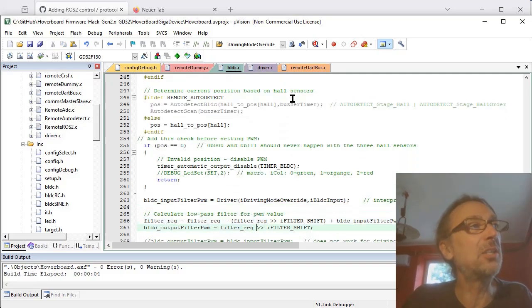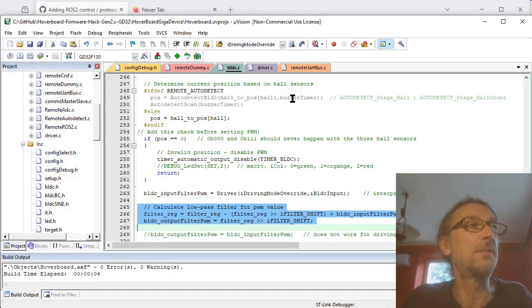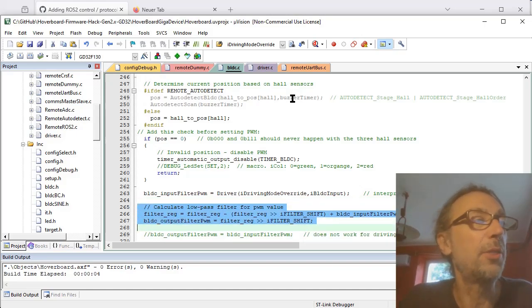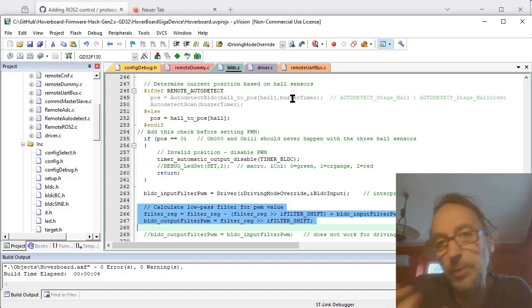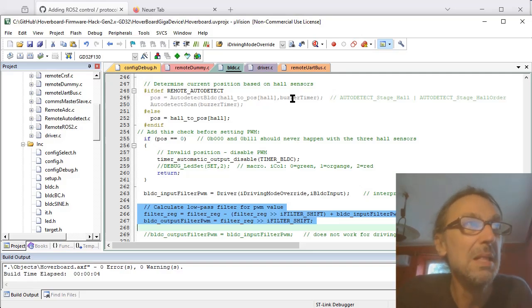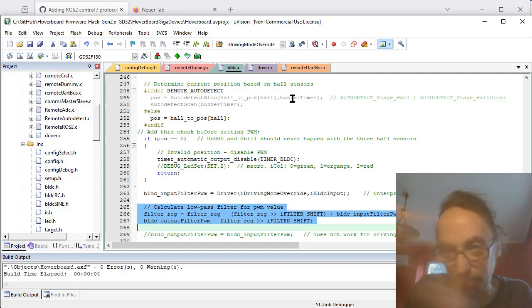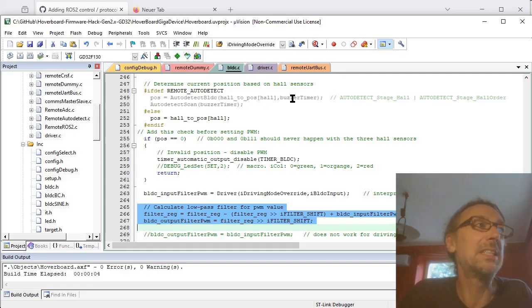And I had to leave this low pass filter with rank 13 right now. Usually I would say the PID control loop will not need a low pass. You see, the output should be given to the motor, but no, so it's still in place.